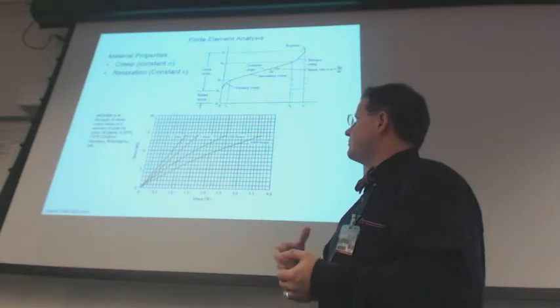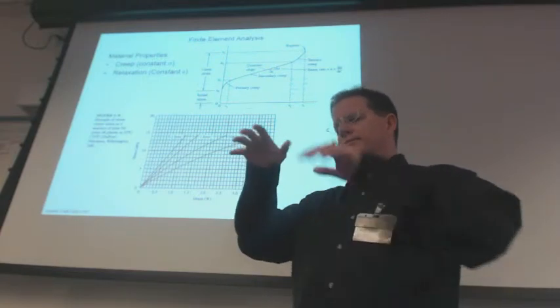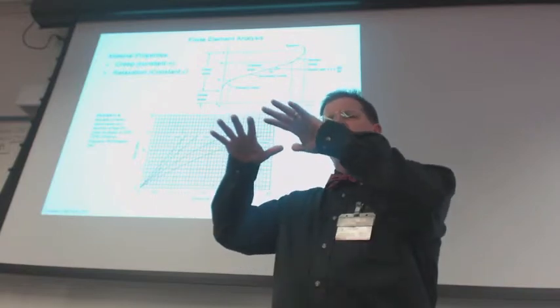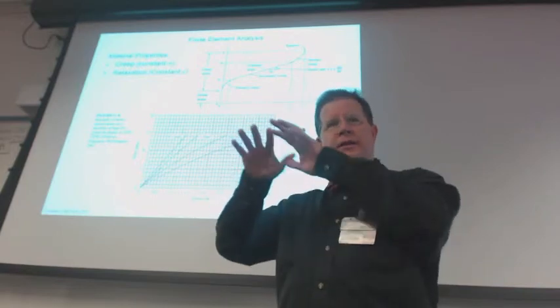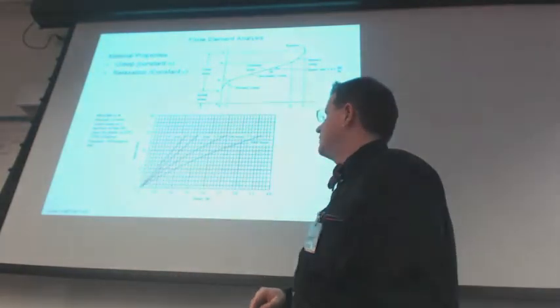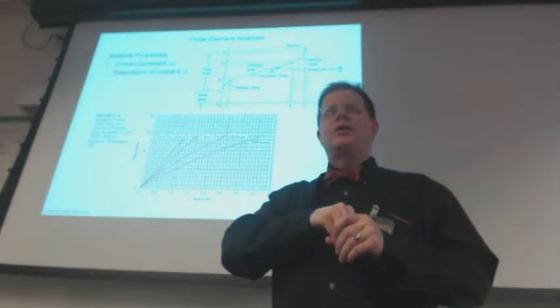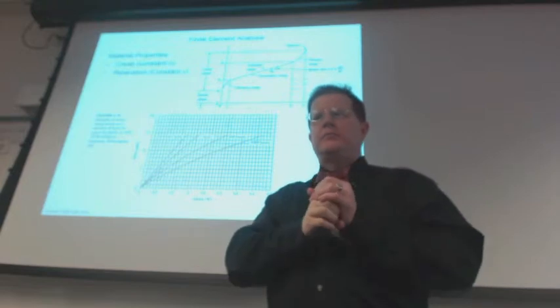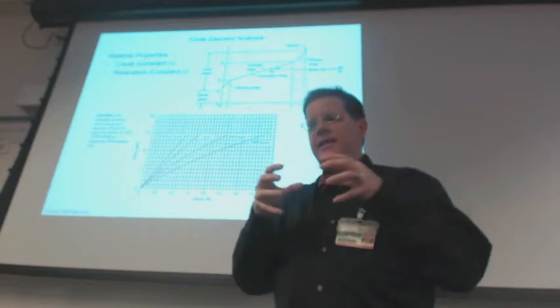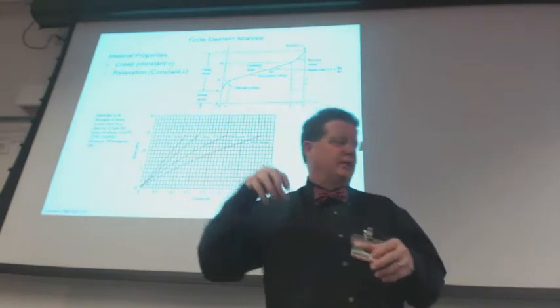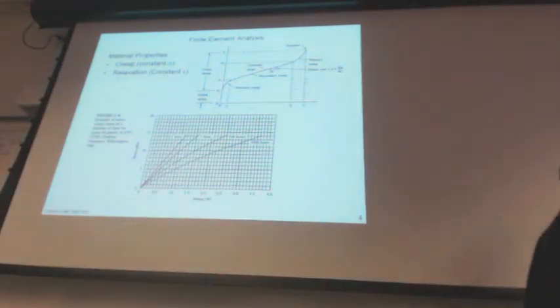But your material, if you have a heavy load on it, will tend to shrink in thickness and squish out the sides, shall we say. Or if you have something pressed into a hole, it doesn't maintain that tight fit. It'll begin to shrink and become loose in the hole.